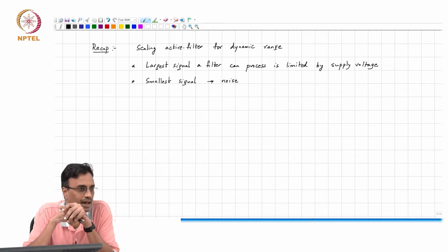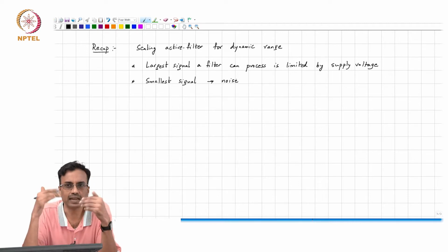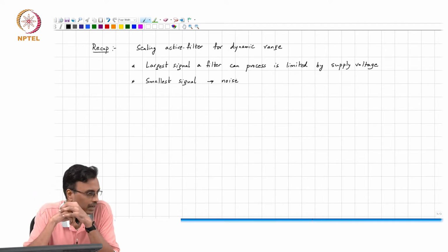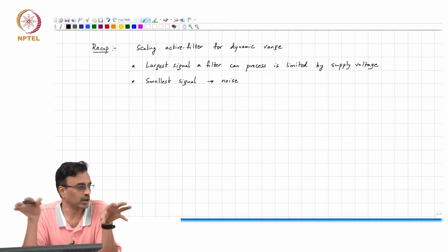All right. And we saw yesterday that the transfer function from the input to various internal nodes in the filter can have frequency response magnitudes, whose peak responses can be widely varying, and as a consequence, one of the op amps will prematurely limit the maximum signal that the filter can process, even though the other op amps are actually quite okay.